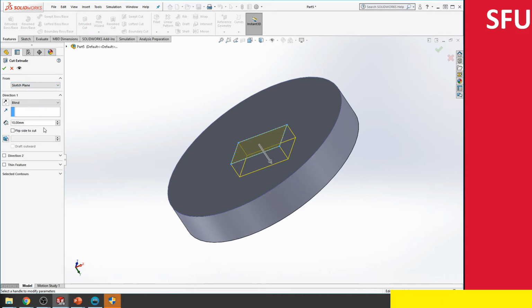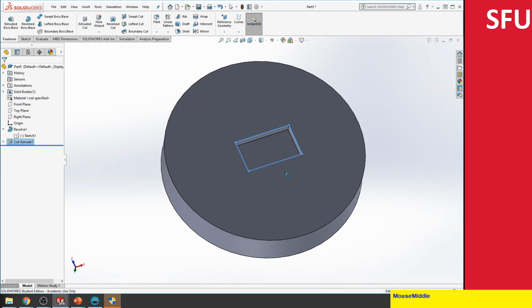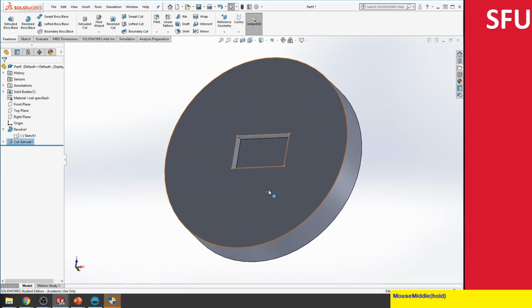Here there are different options. You can either give a distance or I can say just cut through everything. So let's give a smaller distance, maybe 5 millimeters over here, and then say okay. So then it creates an extrude cut here. And if you're actually manufacturing this part, you can't create that sharp an edge. So you can use this feature, which is a 3D fillet. It just makes the surface nicer once you're done with it.